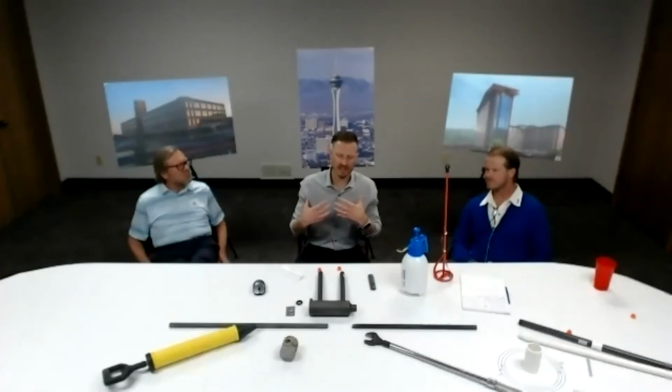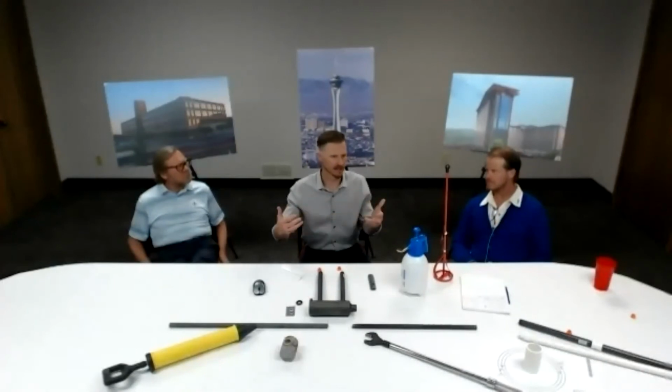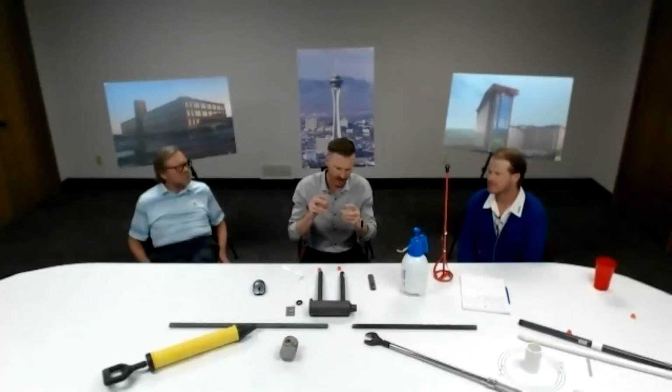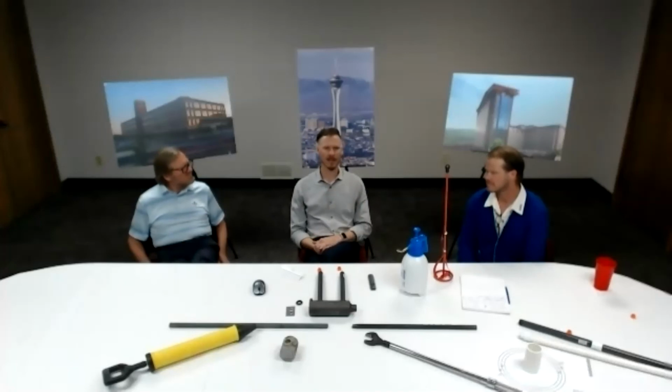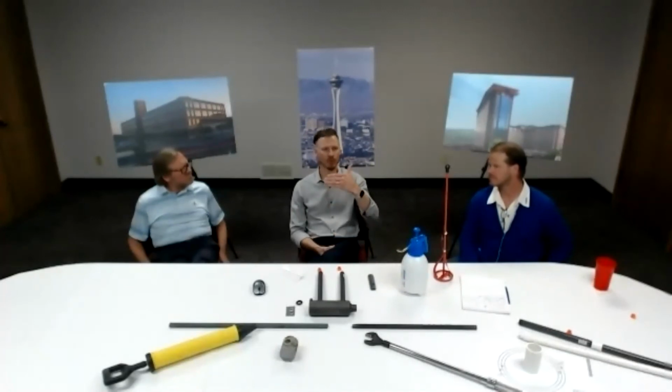I think we as structural engineers like shear keys, and a lot of the projects that we have been working on do have shear keys. If the cantilever is designed to take that shear, then a simple shear key is going to be fine. The other thing that we have seen is that our rebar, because of the way it fits in, is also helping hold up the slab itself, and there's not a lot of movement, is what we can tell. So there's probably more to come on that in the future. But right now, our position is really that if the PT was designed a certain way with the standard pour strip, you would really reshore and shore the same way you would with ours.